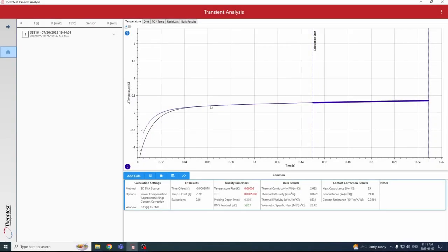In this section of the TPS training, we will discuss selection of test time. Selection of test time satisfies multiple purposes, the first being the penetration depth. We want to select a time that penetrates deep enough into the material that it is truly representative. Of course, this is most critical when you have non-homogeneous materials. Reason number two, to satisfy the total to characteristic time, or TCT.